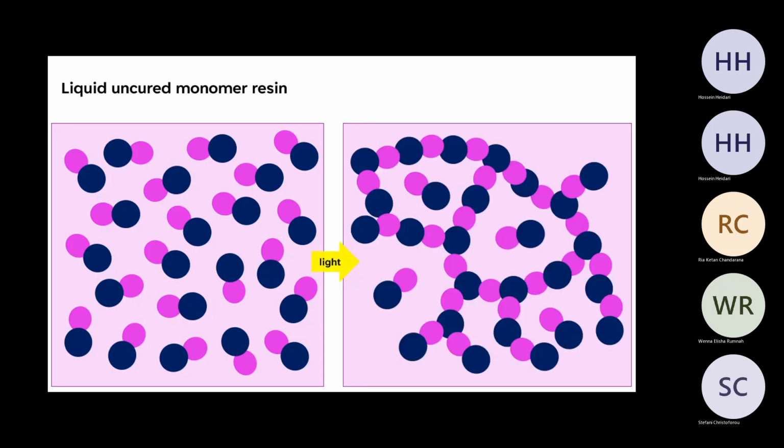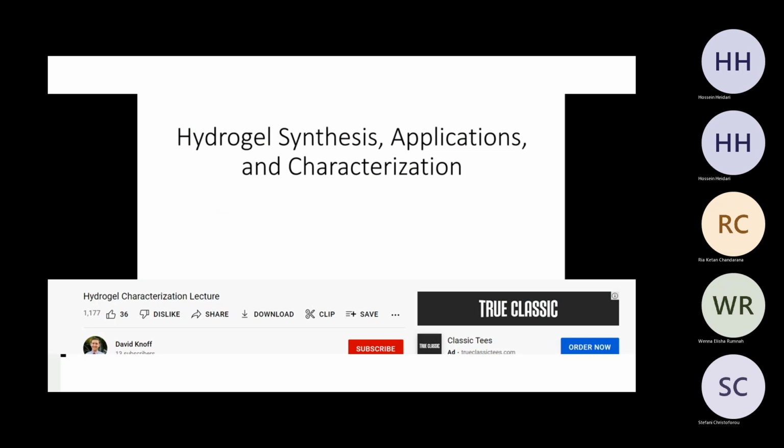So as I explained, the reason that happens is when you're curing this object, you're cross-linking the majority of those chains, but a bunch of those stay as single monomers, and so they can escape that environment as soon as the solvent hits them. Now, if it's a very weak solvent like IPA, it can only penetrate the surface a little bit and get the residues off. But if it's a strong solvent like acetone, it actually goes all the way in and basically takes everything out of it. So basically, you've got about 1 day to do that. You'll see that a lot of it has already gone.